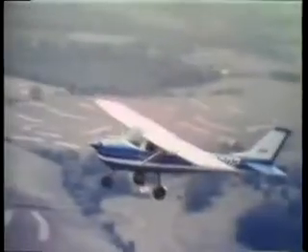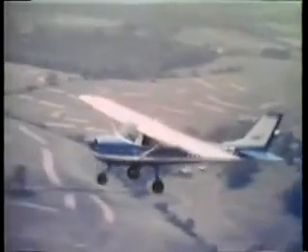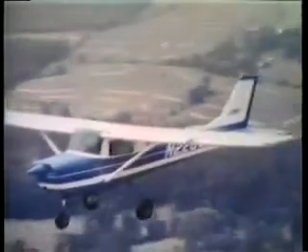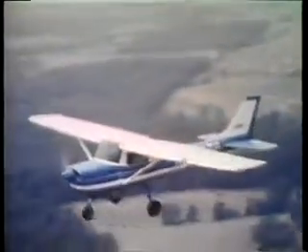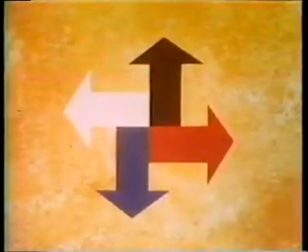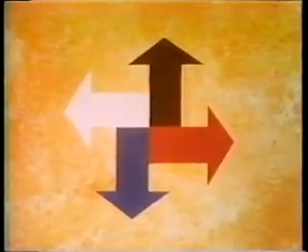In steady level flight, all forces are in balance. Thrust equals drag and lift equals weight. And this forces-in-balance relationship is so important a principle of aerodynamics that it too should have one of our tags. Let's make it with 4 equal arrows for lift, drag, thrust, and weight. But let's not leave our discussion of these forces without noting that they may be acted on or influenced by outside factors.